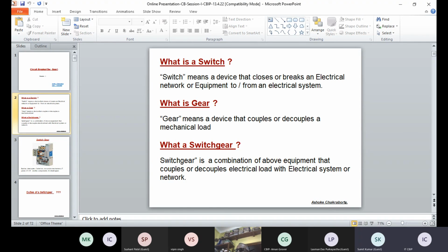But arcing is basically a kind of ionic discharge, the discharge of energy which was inherently stored in the reactive element of the particular load. Whenever any switch is switched off, for a small load you don't notice it. For a big load you will notice. For a DC load you will notice more, because DC does not have a natural zero. AC has a natural zero, so if it cannot extinguish the arc at the first zero, it will try at the second.